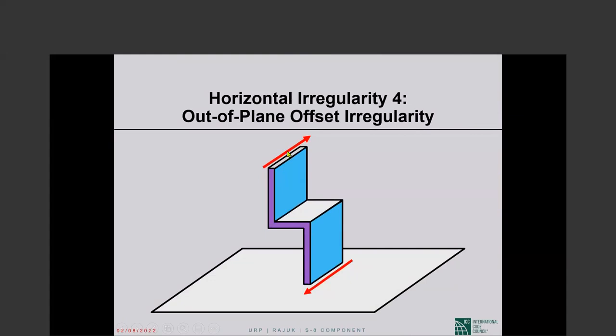Now this shear has an opposite shear at the base of the wall, so that shear will have to go from here to there through the diaphragm. So there will be this shear, there will be that shear, and then there will be shear in the diaphragm.